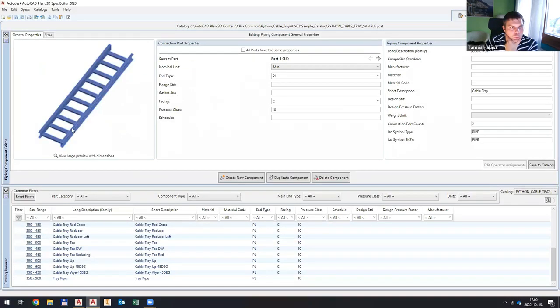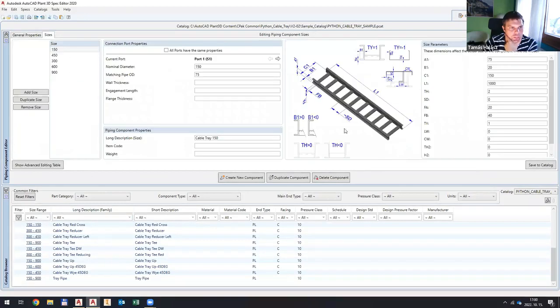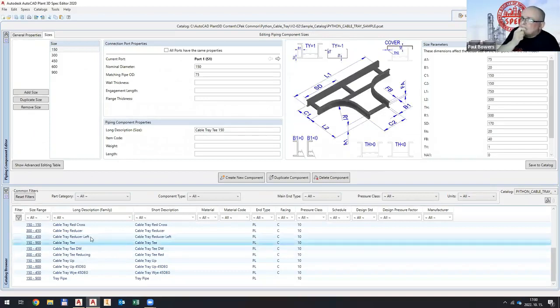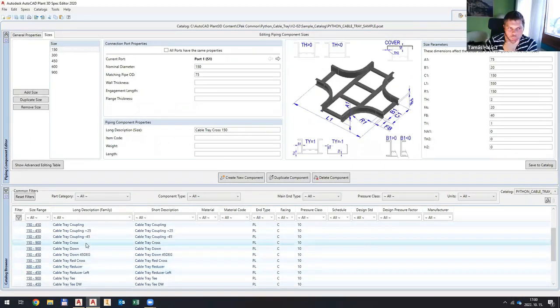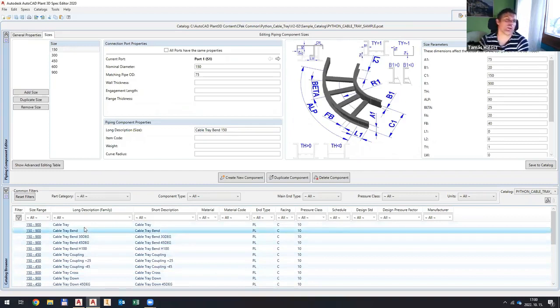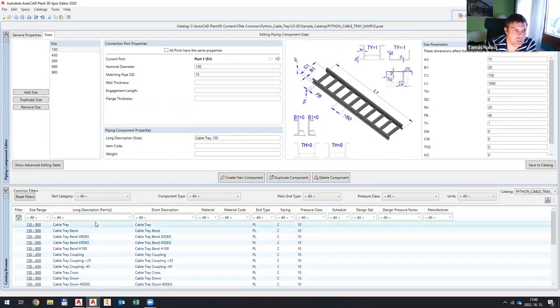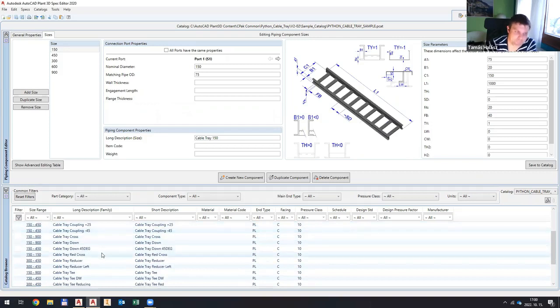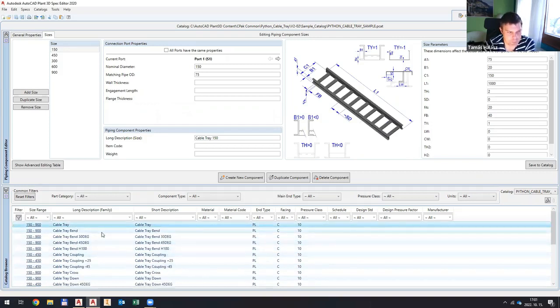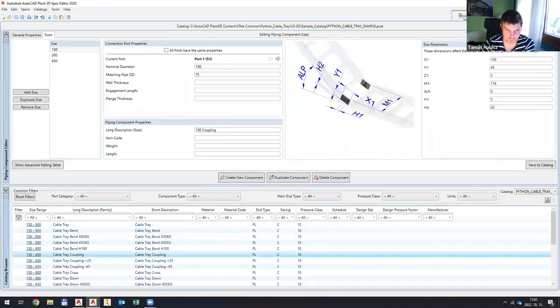With this kind of items, you can create straight cable trays, tees, reducers, whatever you want. And it is working the same way as pipe elements. The only limiting factor is that pipe, as a real pipe, cannot be used in a cable tray. So the straight cable tray is not working like a pipe, it is working like a sleeve. I will show you in just a moment.